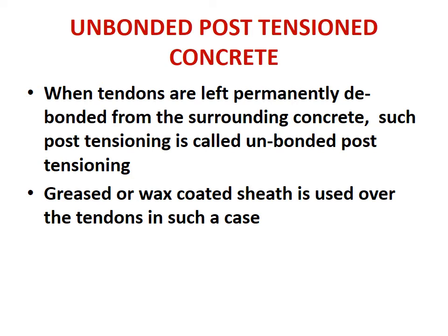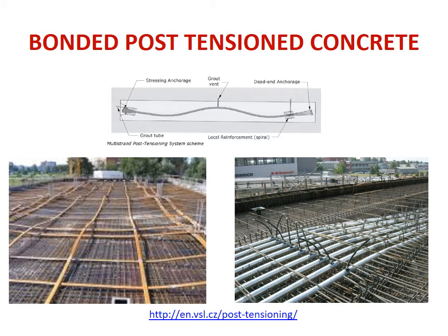You can see the bonded post tension concrete in the upper figure: on one side it is the dead end, on the other side it is the stressing end, and the sleeve or duct is given some camber upward.